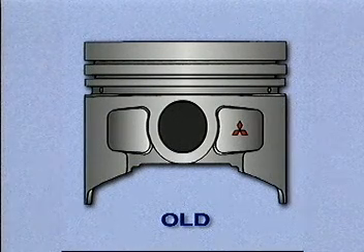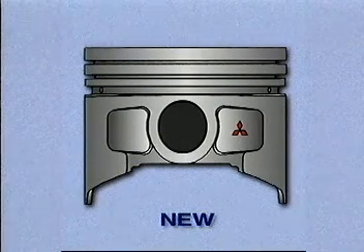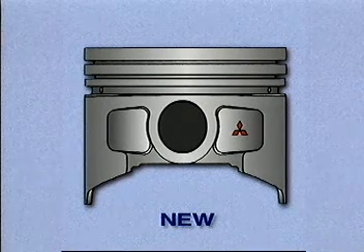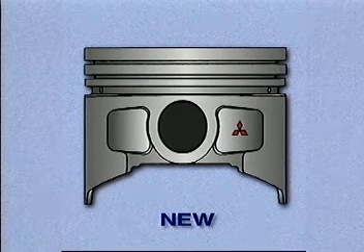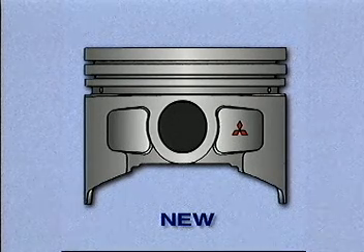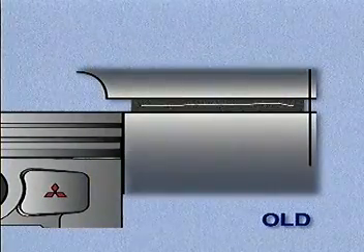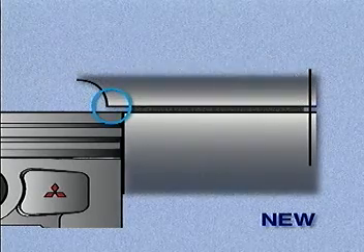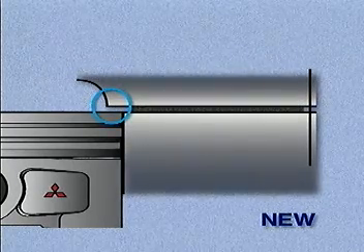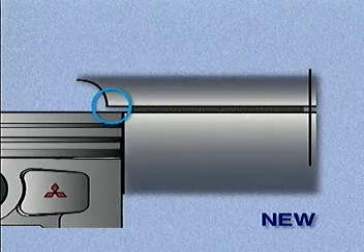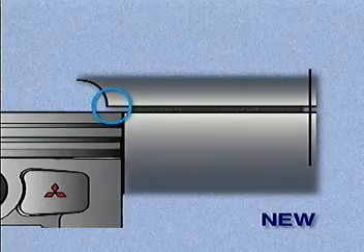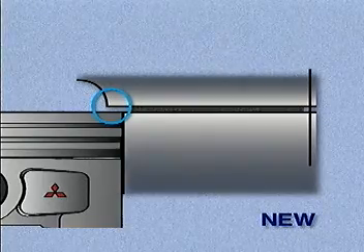vibration. Both engines use a new piston for 1997. The piston design minimizes the distance between the top ring and the piston crown. This reduces the amount of unburned hydrocarbons in the combustion chamber, resulting in more complete combustion and a cleaner exhaust. And a new cylinder head gasket is used on both engines. The gasket has been changed from a carbon material to a multi-layered metal gasket. This design decreases the volume of unburned gases trapped between the cylinder block and the cylinder head, resulting in less unburned hydrocarbons in the exhaust.